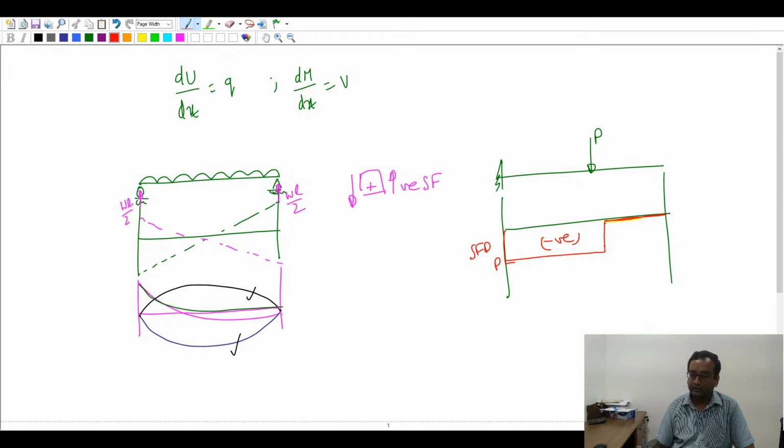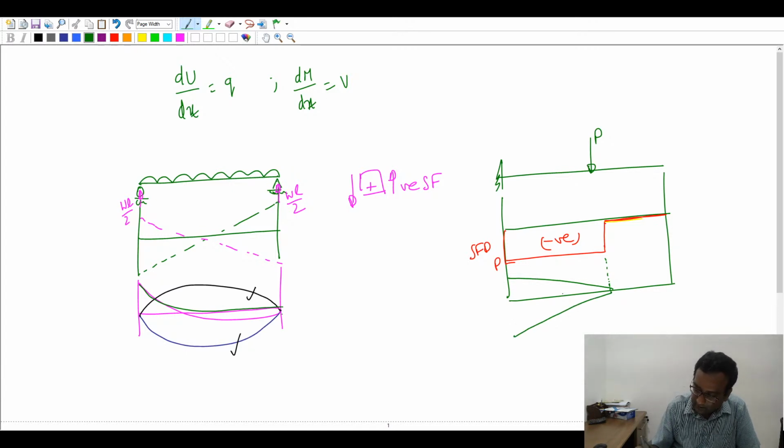Okay, a shear force diagram is a constant, so bending moment is going to be a linear variation. The linear variation can have, when the shear force is 0, the slope is also 0. Okay, and there can't be a bending moment in regions where there is no load, or no reaction forces. So now the question is whether you want it to be like this or like this, for the bending moment diagram.